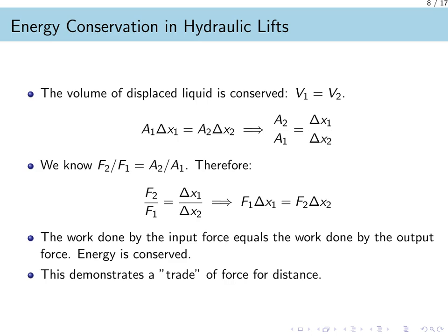While a hydraulic lift provides a significant mechanical advantage, it must still obey the law of conservation of energy. We can demonstrate this by looking at the work performed. Because the hydraulic fluid is incompressible, the volume of fluid displaced by the small input piston, V1, must equal the volume that moves the large output piston, V2. Since volume is area times displacement, this means A1 times delta x1 equals A2 times delta x2.